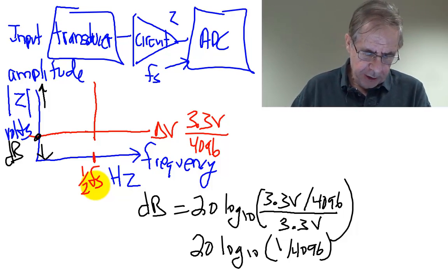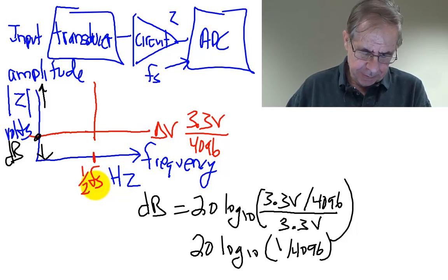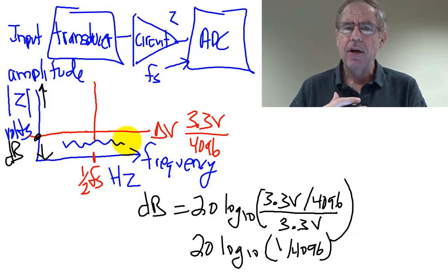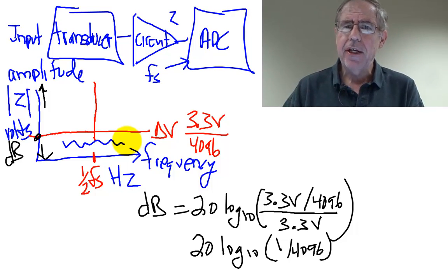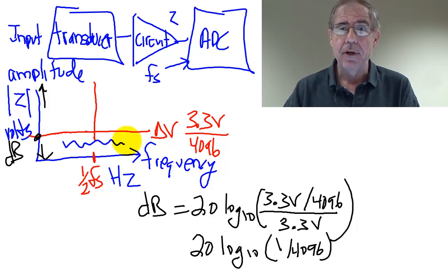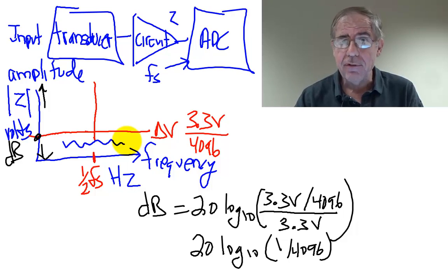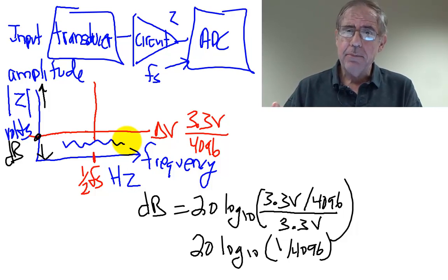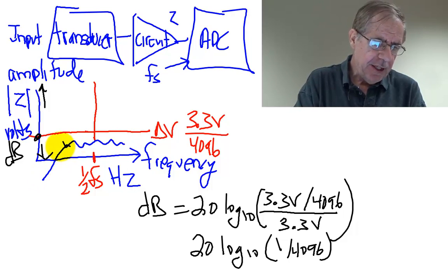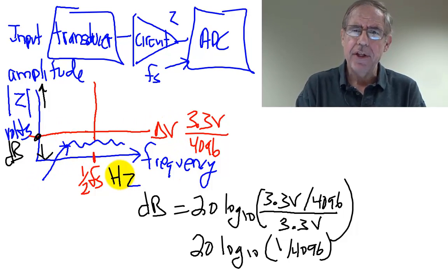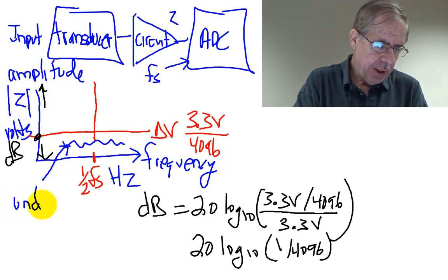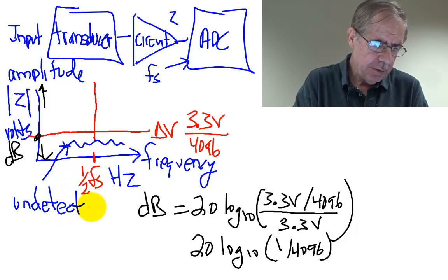If we look at the signals here, what if the input to the A to D converter oscillated less than a millivolt, less than 1/10 of a millivolt, at a microvolt, a picovolt, a nanovolt? The digital samples would not see that oscillation. So we're going to classify this region of the spectrum as undetectable, and not worry about it.